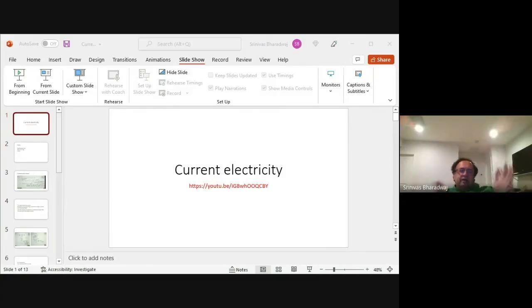Otherwise, you just calculate the net voltage. If you have a single loop, it's a series, right? Net voltage is 4 minus 2 divided by the net resistance. Net resistance is 1 plus 5.3 plus 1.5, or this is 5.5. So you end up with a value, right? So very, very simple. Power is V times I, V squared by R, I squared R.